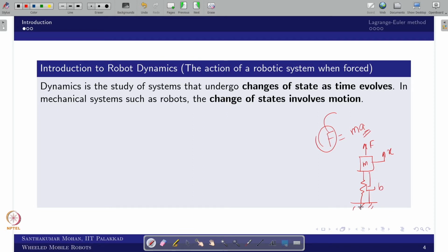B is the damping constant and K is the stiffness. You would write F, the input, in terms of the time derivatives of the displacement: the zeroth, first and second derivatives, that is, b x dot of t plus k into x of t. On one side you write F, and on the other side is a function of x, x dot and x double dot.